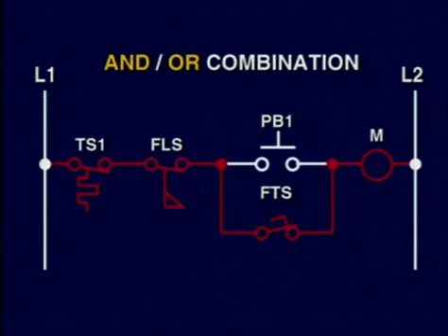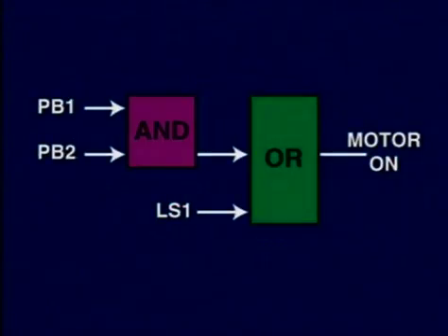Notice that the logic simply follows what we want to happen, or in other words, the conditions that we want in order to turn on an output. So, if you are modernizing or revising a control circuit for the activation of an output device, just write down using the AND and OR logic to set up the conditions.